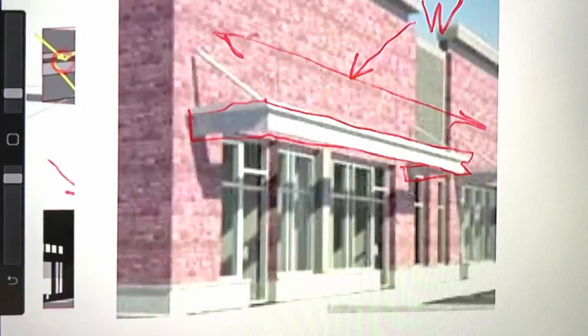However, if you remember, I said that this face was facing the west. So the western sun starts to penetrate the space with its harsh sun, especially in the summertime, while this canopy, which is kind of void from the middle, will not have any serious impact on the space inside. Now, to start with, the orientation here is not favorable because you're exposing the length of the building to the harsh